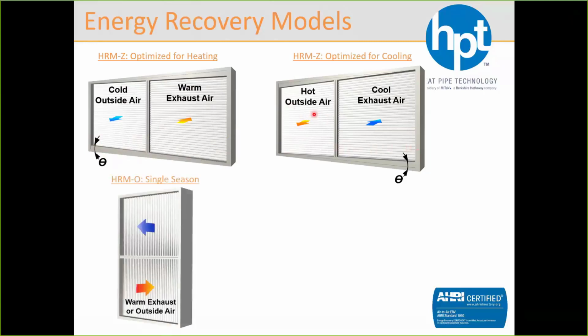And followed by HRMO, and O actually stands for over-under. This is where you have applications with stacked airstreams. This is single season recovery. It is going to give you the best recovery out of all the models that we have. But one thing that you have to consider is you want to make sure you have the correct airstream on the bottom.